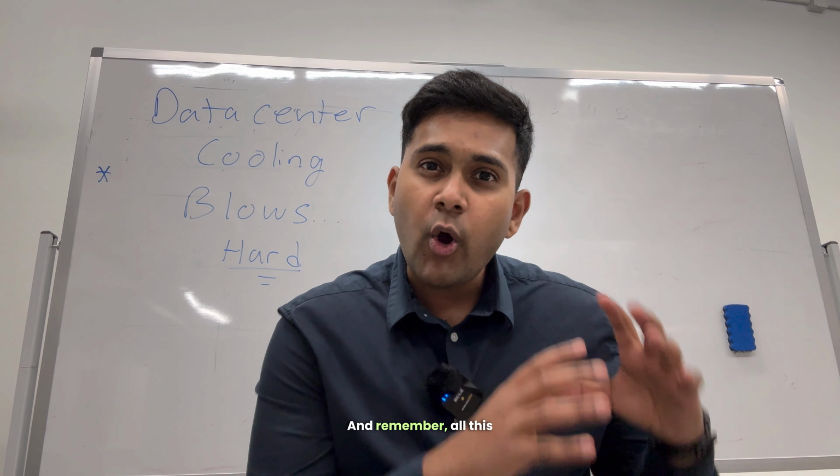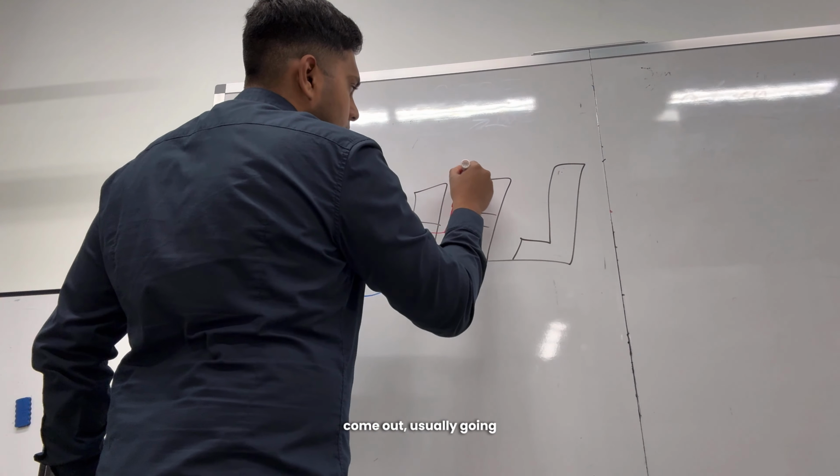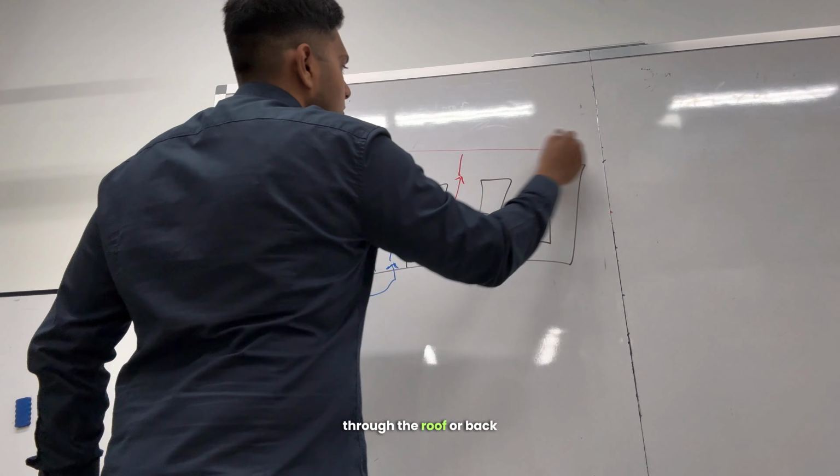So here's the problem with traditional data center cooling. You'll have a raised floor where servers and HVAC equipment will be placed. So here's your HVAC, here's your servers in the middle. These HVAC systems, called CRACs, will send cold air underneath the floor. The cold air will go through the servers, they will get heated up, and they will come out, usually going through the roof or back to these HVAC systems.